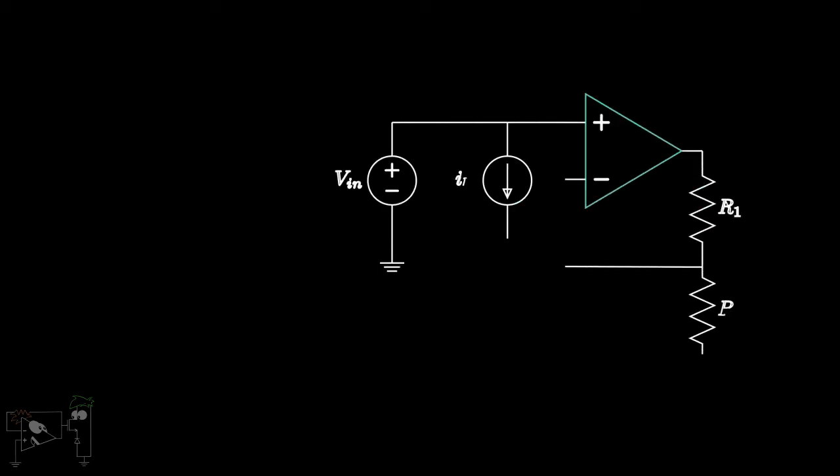Let us study the effect of the input bias currents on the non-inverting amplifier. Note that, whenever we analyze an op-amp for a non-ideality, we assume one non-ideality at a time. Hence, while studying the effect of input bias currents on the op-amp, we consider all other parameters such as zero offset voltages, infinite input resistance, infinite gain etc. intact. As shown, IB1 has no effect on the circuit because it flows through a voltage source.